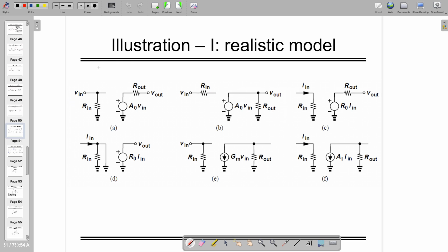So the first one is a voltage amplifier. I'm going to write just V or VI, GM, or the impedance. This is voltage, right? This one is also voltage. This one is voltage and input is current. Look at this, so V out by I in is making impedance. This one, V out by I in, making impedance. This one, look at this quantity, it's current, output is current, and the input is voltage, so it's transconductance.